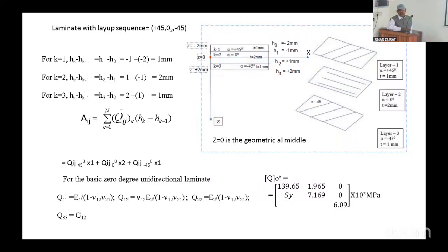In actual composites nobody will put 1 mm; composite material thickness is 0.1, 0.2 mm. I have purposefully put 1 mm for easy calculation. Decimal points we can avoid. Second, if you have more thickness, buckling will not happen for the shell; it will fail by compression only. Because of all this, I have put 1 mm for the sample problem.